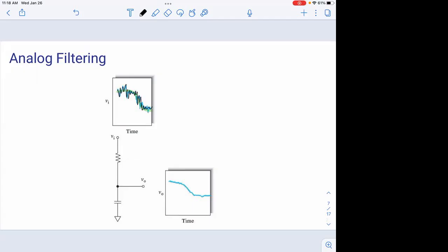So this would be a theoretical diagram, right, of an RC low pass filter. And so what happens is that low frequency component, so that's the one that's in green, passes through no problem, right? So you still see that general waveform. It looks kind of like this. But what we've done is we've gotten rid of much of the noise that used to look like this, right? So we got rid of that. See you later. And now I have this relatively smooth waveform. Right? So this is the effect of a low pass filter.